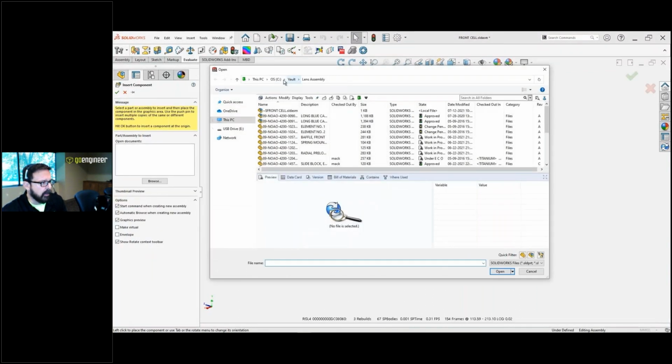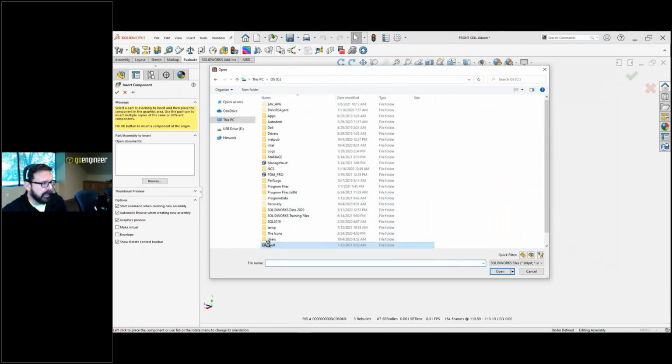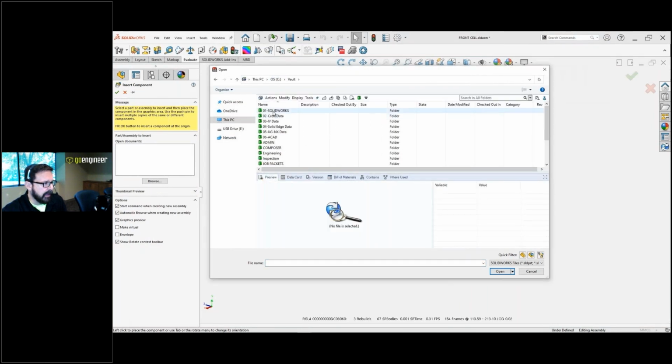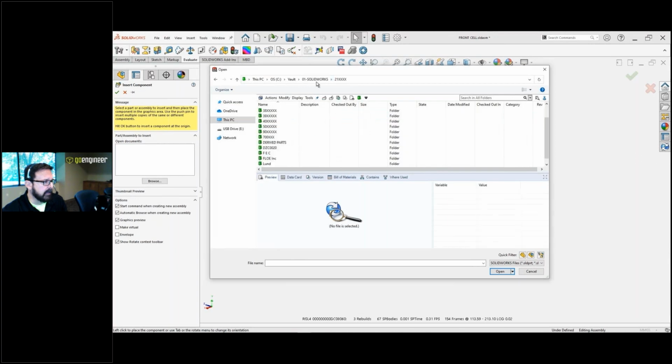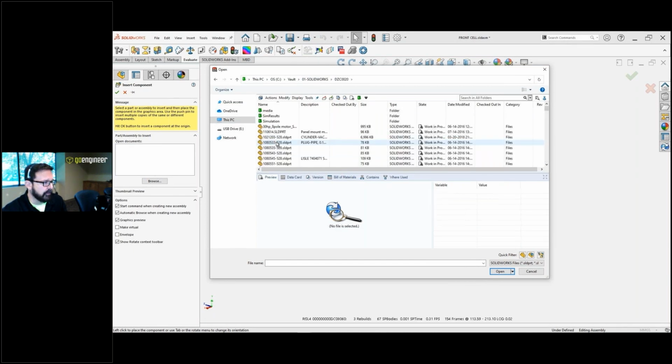So you're using PDM and you're inserting a component, and one of the beautiful things about SOLIDWORKS PDM is one of the main ways we interface with the Vault is what you're seeing, Windows Explorer, and we're all used to it. We all use it, but unfortunately, people get comfortable with that, and they go through this workflow where they're just whapping through folders up and down, looking for the part they're trying to insert. Oh yeah, it's this folder.